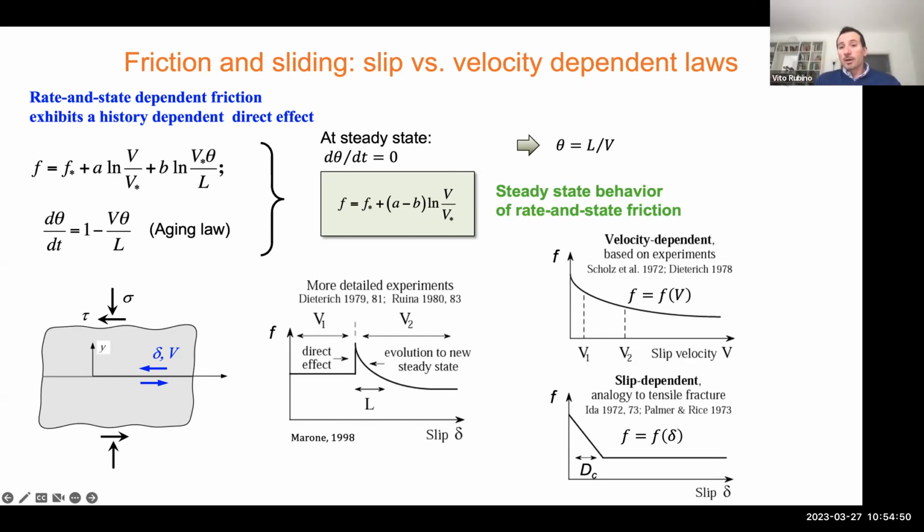Okay, what we measure are displacements. Then you get strains by spatial differentiation, and then stress using constitutive properties. Then we look at the stress along the interface, because we can measure pixel by pixel, so we have a line of pixels right on the interface. By taking the ratio of shear and normal stresses right on the interface, we get friction.